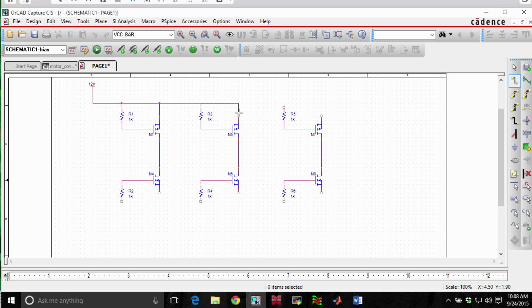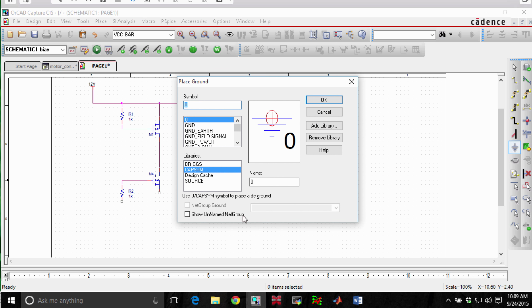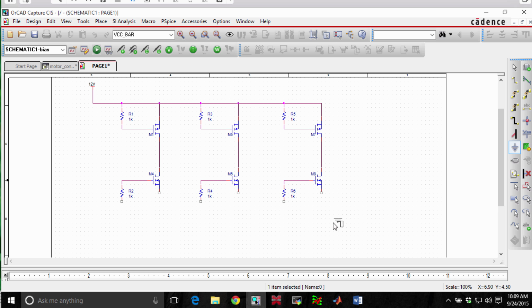Now remember, schematics are very logical connections, so the way I'm connecting them here has very little to do with the physical layout. We're really after the connectivity between the points, not the actual physical paths that will be connected later on. So there's the power side of this H-bridge. The bottom side of this H-bridge is going to be connected to ground. That's going to be down here as a G. And there's pretty much only one universal symbol for ground, and that's it. So I'm going to go ahead and connect these guys. Again, I'm just using the W key to rapidly draw these lines. To get out of an insert mode, I can hit escape, like that. So there's the connectivity for the MOSFET H-bridge.